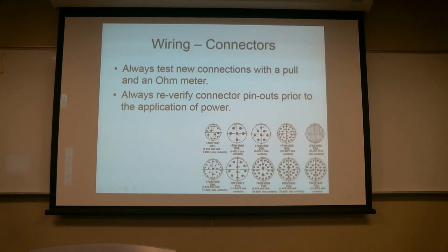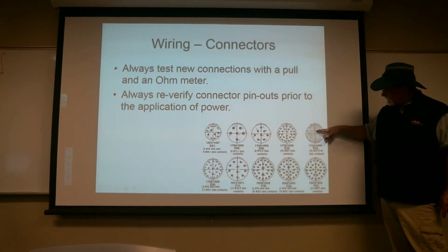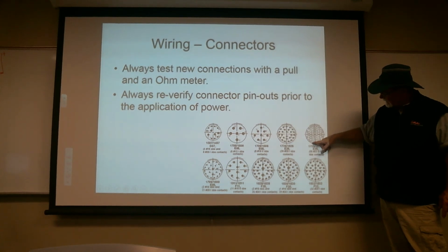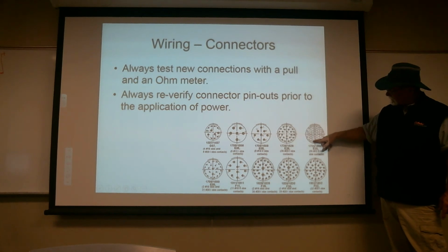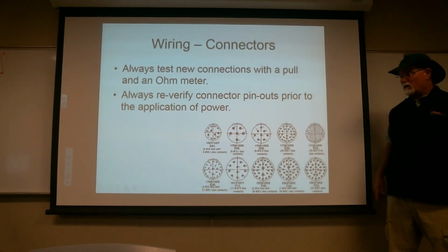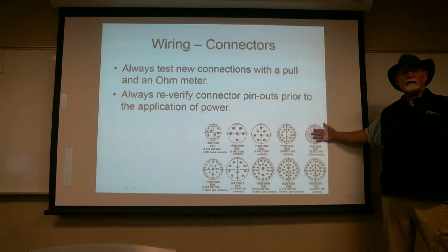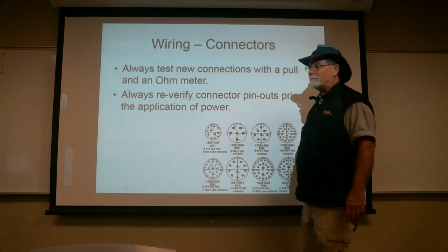In general, they're pretty good about embossing the pinouts on both front and back. However, it can be pretty difficult to fit numbers in there. So here you can see they started with a number and ended with a number, but in between the 8, there's 6 unnumbered. So you kind of got to do some counting. And if you're building up that whole harness, and building up harnesses like this takes days. This is not a quick job.